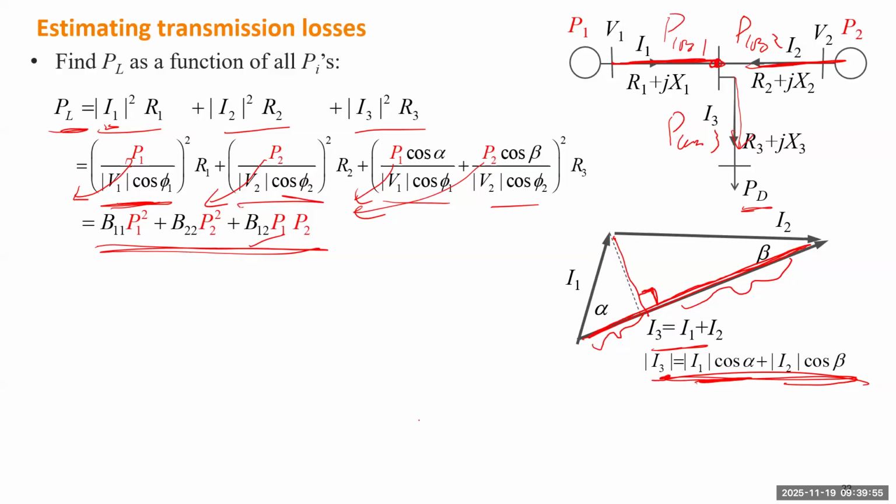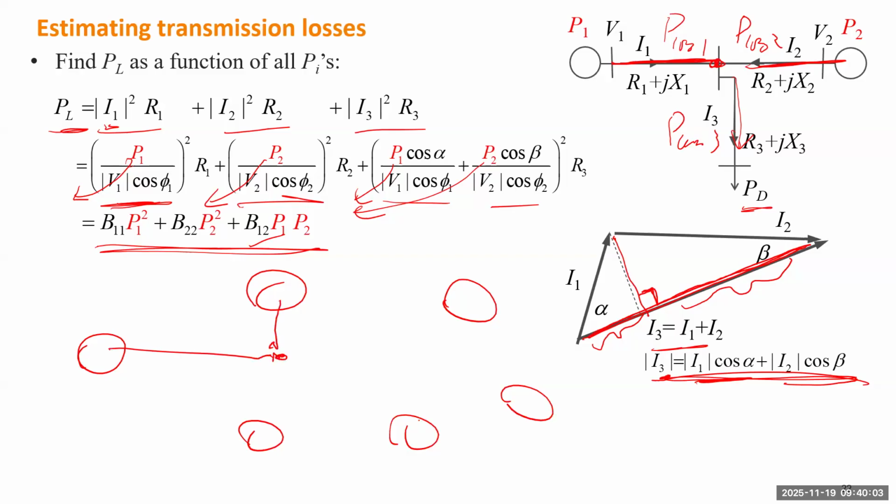Which means even if you have a very complex network with many distributed generators which together power a load center area, for this case the transmission loss function will be very simple. The cross dependence between the generator outputs can be ignored if this is the case.